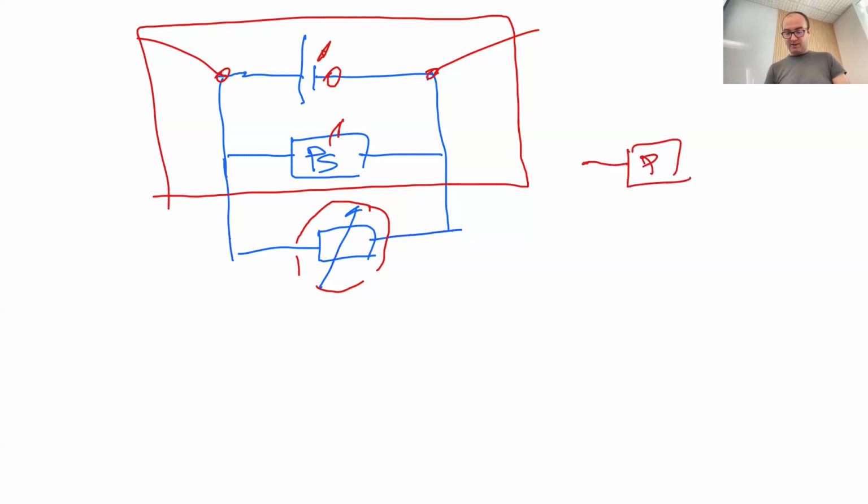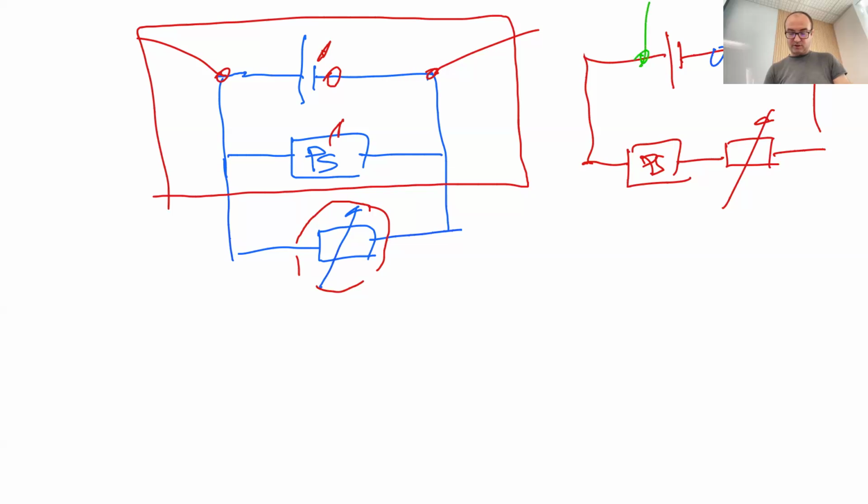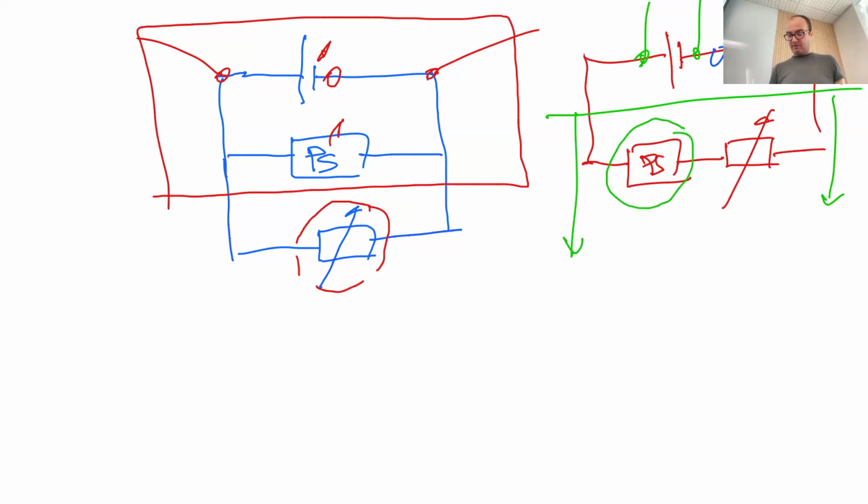So there is a power supply here, there is the electronic load here, and the fuel cell. Current is measured here. The current is the same, it doesn't matter. And we measure the voltage at this point. That is the way, because now all these two are in parallel on one side and in parallel on the second side. There will be influence of this undoubtedly. And that is why, whenever we look for a power supply, I was asking you what kind of power supplies you have in Dijon, because of its bandwidth.